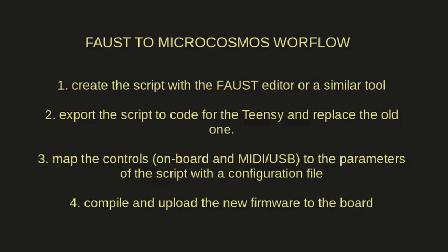On the Microcosmos, there is a special program called Microcosmos Faust program. It is a generic way to manage Faust scripts exported for the Teensy board. The principle is straightforward. Create the script with the Faust editor or a similar tool. Export the script to C++ code for the Teensy and replace the old one. Map the controls onboard and MIDI USB to the parameters of the script with a configuration file. Compile and upload the new firmware on the board.